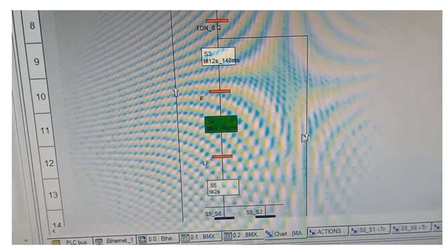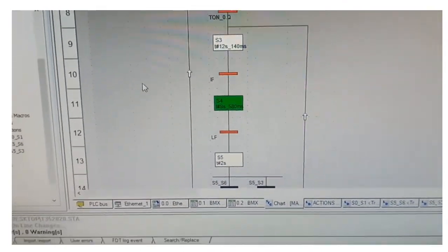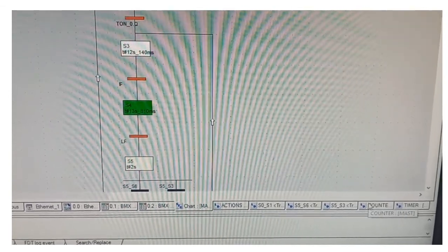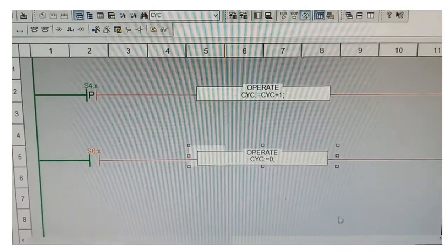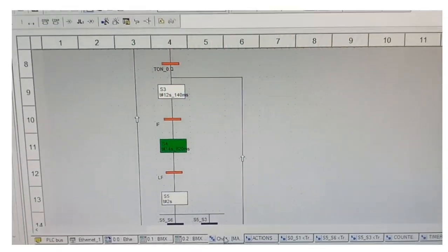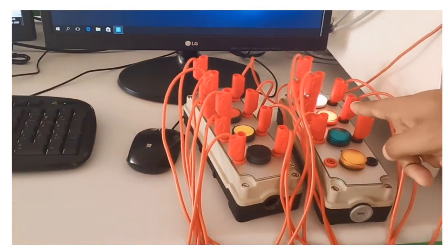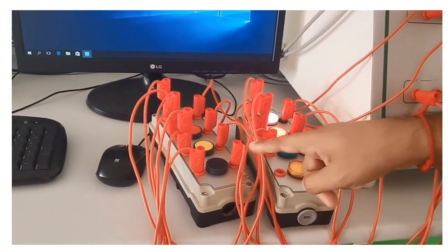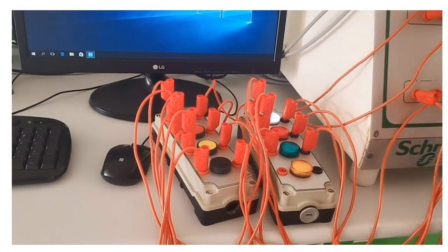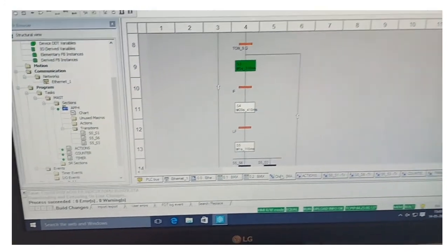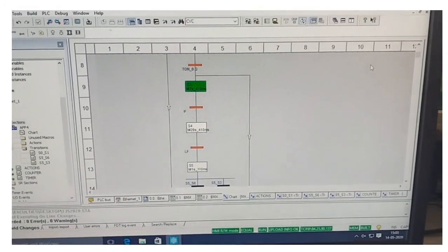As of now only 1 cycle is completed. So it will check for the cycle. Now once again it will go for the low position switch after this, because the cycle is not completed, right? So it will come to the low position. Because the cylinder is in the intermediate position, going to the low position, I will check the low position. Now 1 minute drilling is done. So twice the drilling is done. Now once again it will go up and it will reach the intermediate position.